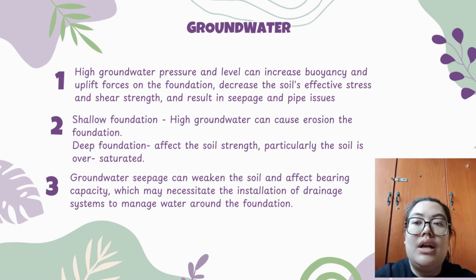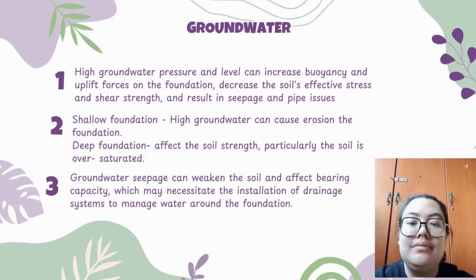Third, the groundwater seepage can weaken the soil and affect bearing capacity, which may necessitate the installation of a drainage system to manage water around the foundation.